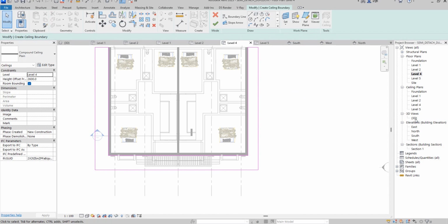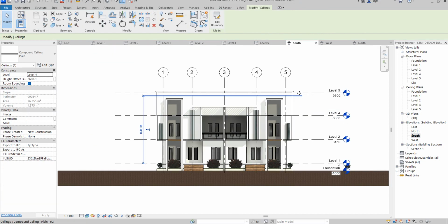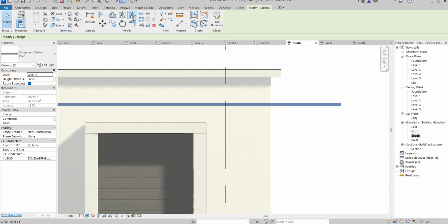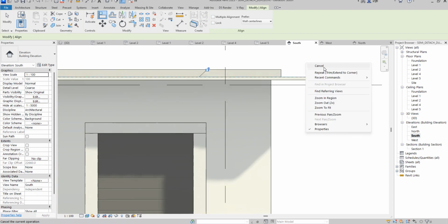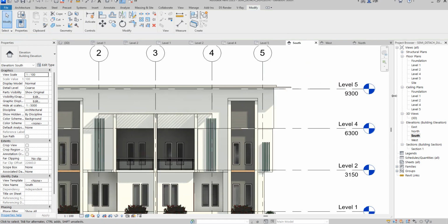So this is it. So I'm going to go to start elevation before I click finish. When I click finish now, you see this particular one. So it's supposed to align, attach to this one. So that's what I want to do. I'll just click in and say attach. So now I need to delete them so that we follow the same coping level of that roof.